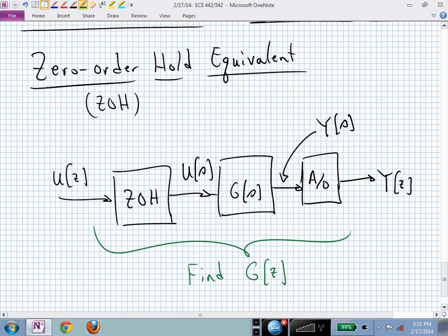And this is different. So somebody will say, oh, you have a system. You need to now know, is that system a plant, which is preceded by a zero-order hold? Then you do a particular discrete equivalent. You do a zero-order hold equivalent. We'll then talk later about just being given a filter and asked to give a discrete equivalent. We'll do that a different way. We won't necessarily have to precede that filter with a hold device.